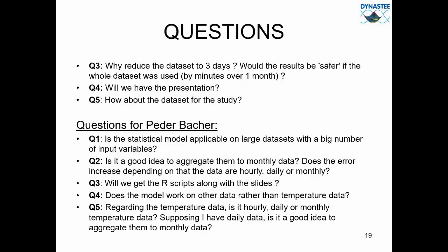So if you're interested in, let's say, the steady state characterization, so the heat loss coefficients and UA value and such, then, depending on your data, of course, to some extent, if you have enough data, you can use average values and use this energy signature or linear regression model and simplify it.